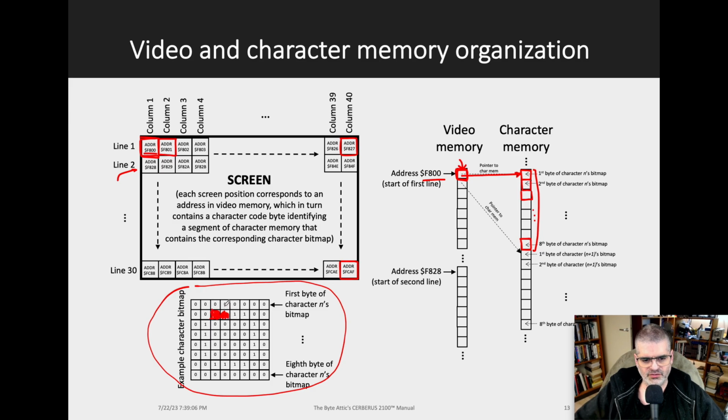And when it's 0, it's because that pixel is unlit or off. So if you look at the position of the 1s and 0s here, you will see that this corresponds to the letter O, non-capital O. Here you go. So you have 8 lines of bits, in other words, 8 bytes until byte 8.